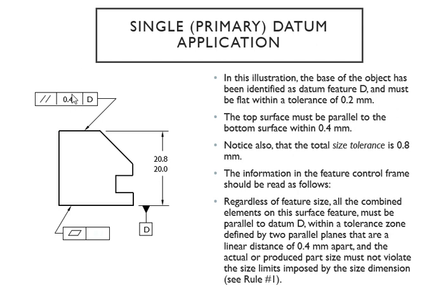That's kind of like your tolerance. It's got to be within that. So here, this is your flatness. So that's a 0.2 right there. And here, this dimension you can vary in between 0.8. Okay, so that's all about what you need to know.